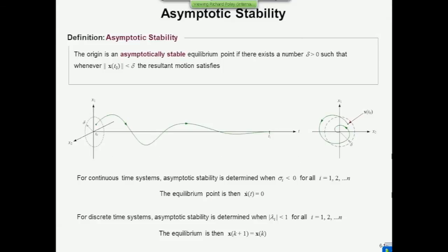Now, I'm going to use this a little bit more in a moment, but I want to go on and talk about stability. There are two types of stability that I want to tell you about before we go on and see how they're used. The first is what we might immediately think of as a stable system. This system possesses the property called asymptotic stability, which means that the initial condition response of its state, as time becomes infinite, will converge on the equilibrium point.